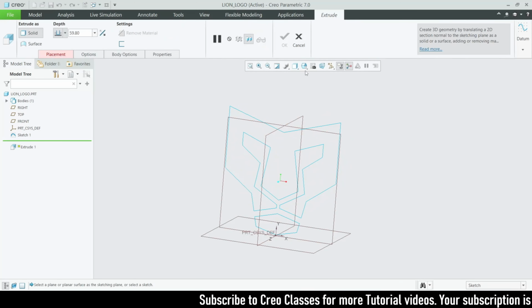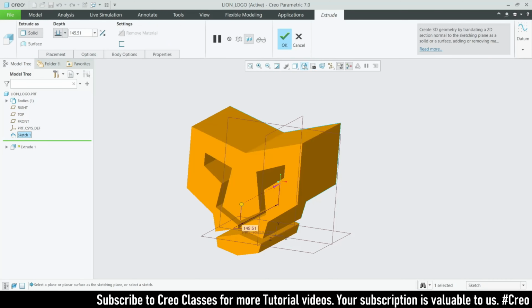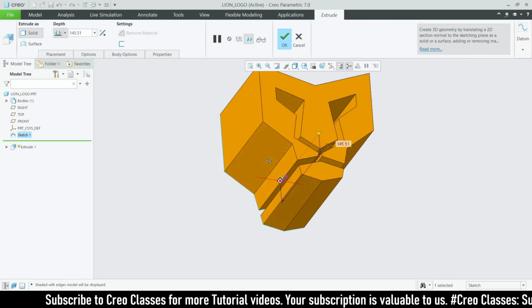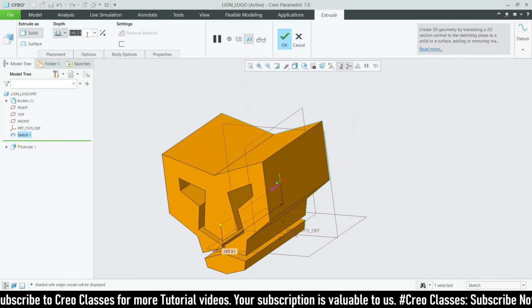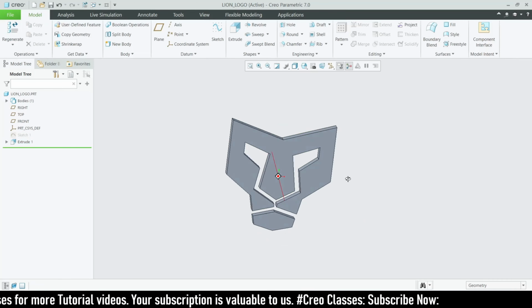So let's extrude this. Oops, sorry, I forgot to select the sketch, and let's go for the extrude, and let's have the shading with edges, and let's have some minimum extruded value of 10, and then let's click on OK.